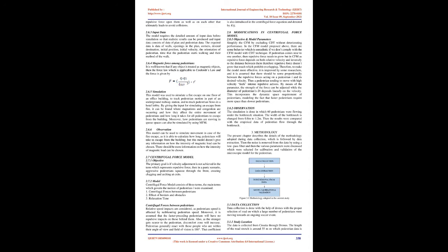Improvements in social force model. By using the above-mentioned two versions of SFM, improvements were made by various researchers: Johansson, Helbing, and Shukla, 2007. Pedestrian shape. There are various kinds of shapes like circle, ellipse, and three circles which can be used to represent a pedestrian. In reality, a pedestrian is best represented by an ellipse, as they have different widths on the two-dimensional plane. Initially, pedestrians are represented by circles in the Helbing escape panic version of the model.